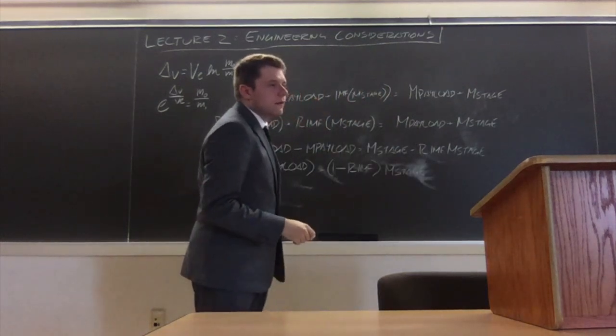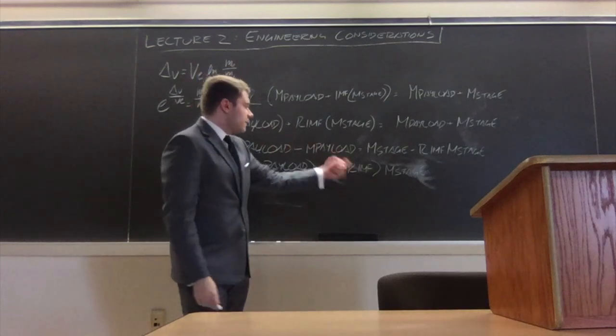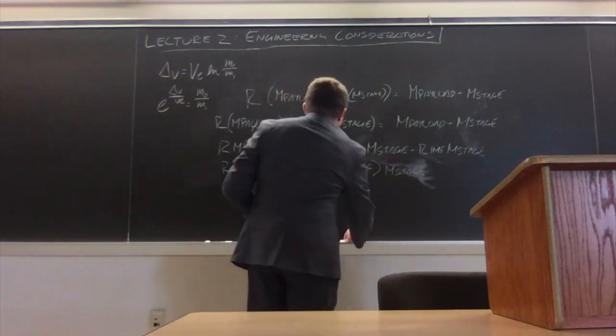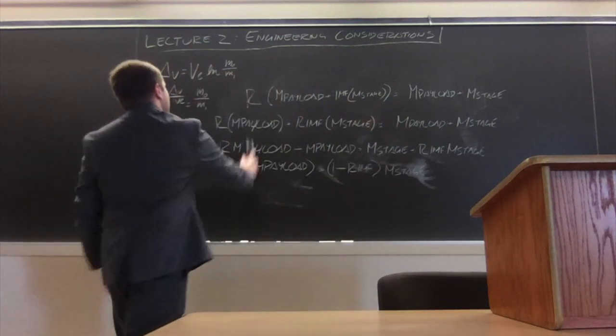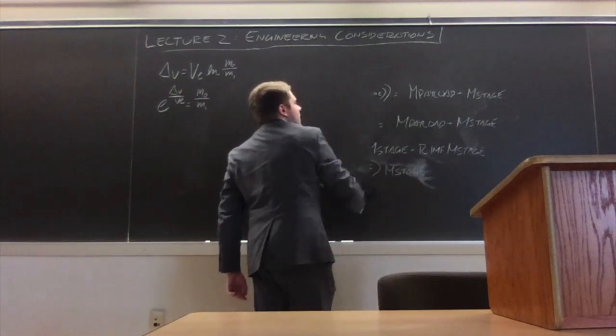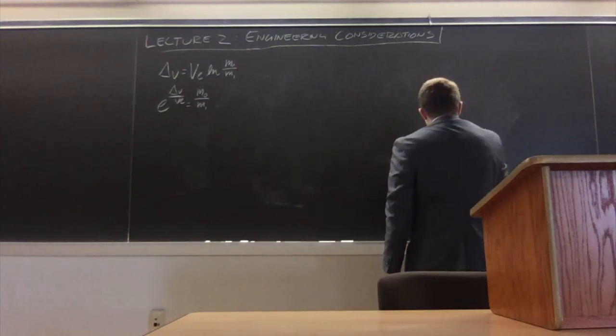And then the final step in this entire process, we can simply take this and put this under that. And that yields the final version of this equation that we're playing with here, where you're writing everything in terms that we can define the mass of a stage for a given delta V with the inputs of our propellant mass fraction and all these other factors.